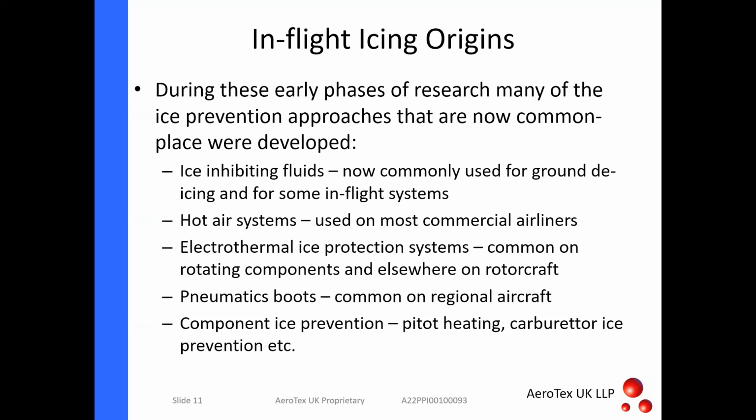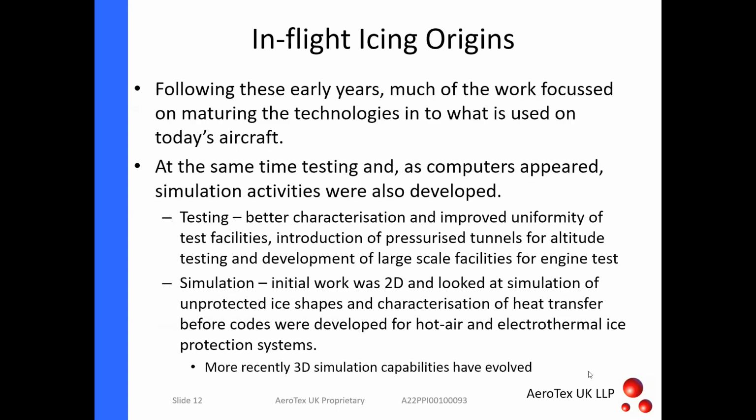electrothermal ice protection systems, which is an area that we sort of specialize in, is common on many rotating components, so on helicopters, propellers, and things like that. The pneumatic boots I mentioned earlier on regional aircraft, and then component ice prevention, so looking at pitot tubes, adding extra heaters there, and carburetor ice prevention, things like that. As I say, this is going very quickly through the background.